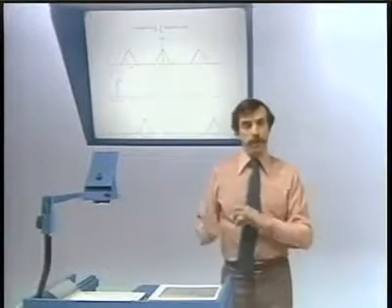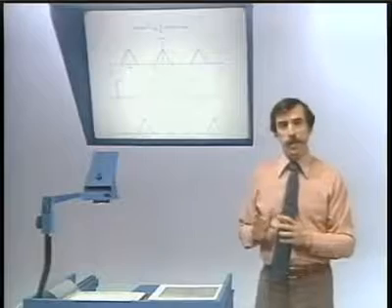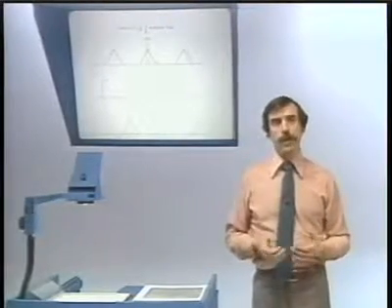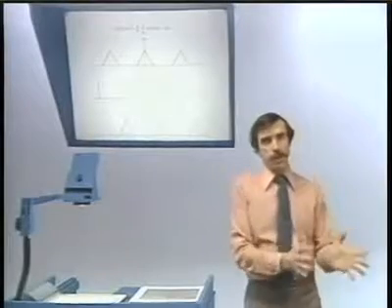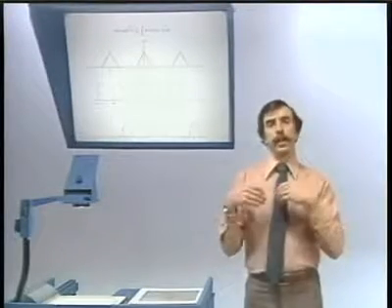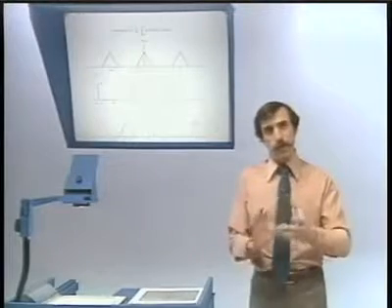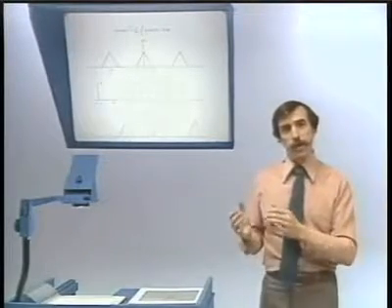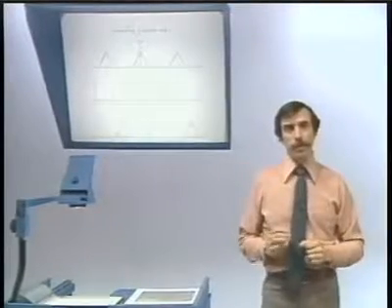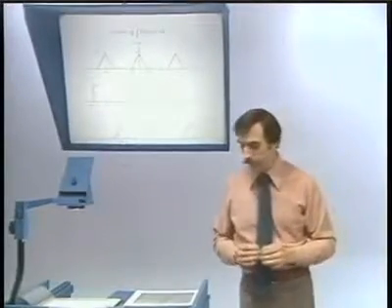So what's happened in the discrete time case with a complex exponential is exactly the same as in continuous time. Namely, we modulate, that corresponds to shifting the spectrum. We demodulate by multiplying by the complex conjugate of the original carrier, and that shifts the spectrum back to where it was originally.